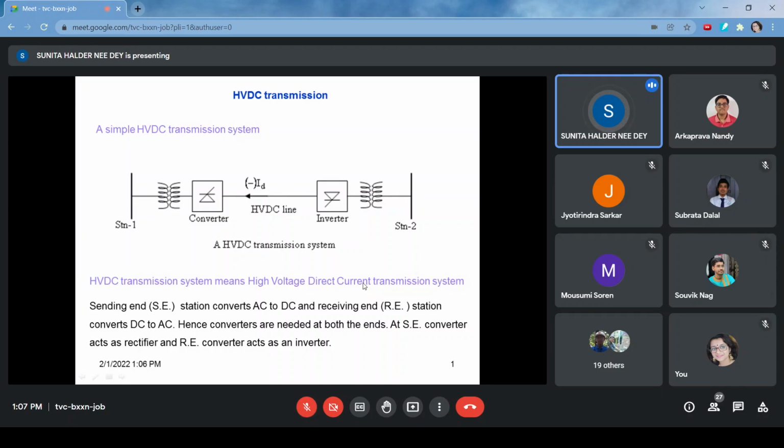Firstly, we can step up or step down the voltage very easily using AC. But that is not so easy in case of DC applications. So that is one limitation. At the same time, when we are supplying current or voltage in AC, the AC current or voltage has a zero crossing, right? Current or voltage will cross zero, and our frequency is 50 hertz. So, this total wavelength is 20 millisecond. Is it not 1 by 50 seconds? So, it is 20 millisecond.